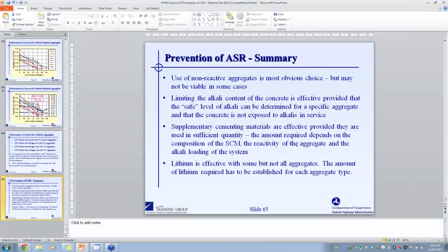It's almost like the pozzolanic reaction again. The initial alkali-silica reaction produces an alkali-silica gel, which will slowly, the alkalis will exchange for calcium. Some of those alkalis get recycled and go back out and cause further damage. And in a large structure where there's no opportunity for the alkalis to leach out of the structure with time, as I say, we've seen expansion continuing even after 70 years of age.